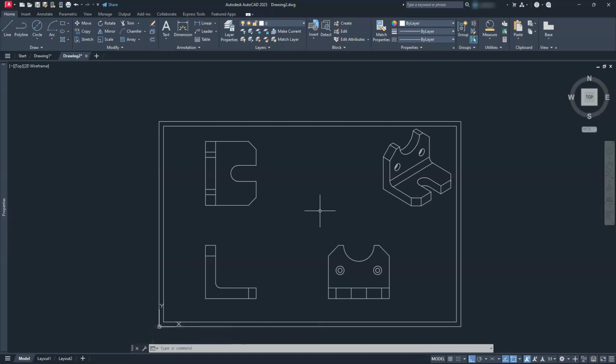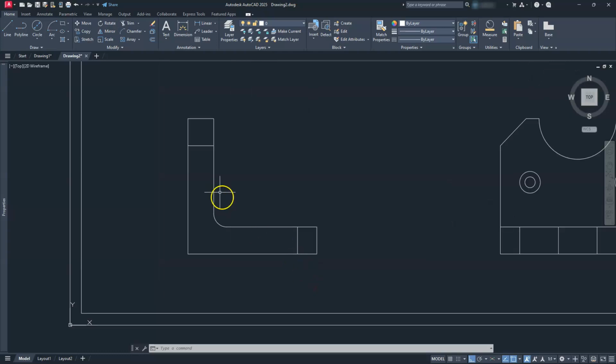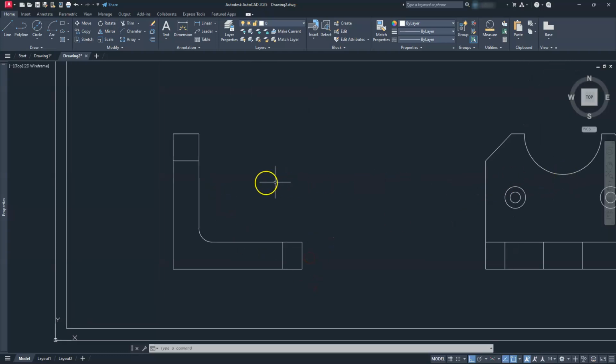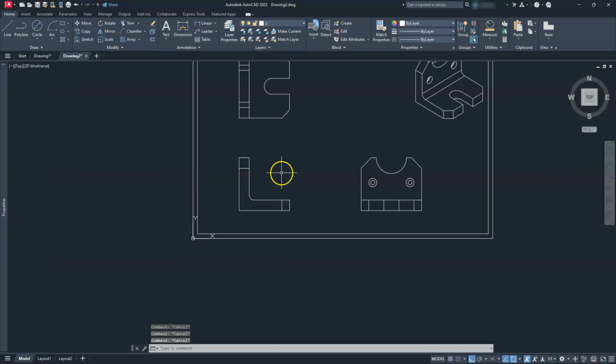But now before I do that, I want to decide, am I going to put these hidden features on here? And the answer to that question is going to be yes. So I'm going to go ahead and start doing that now on this one. When I look at this one, what I do know is that I have a hidden surface right below here, right? This distance going down from here is 30, or I can do a line. I can touch this midpoint, try not to touch anything else until I come here, select this intersection, and go right across to this one. Hit escape, and then this one will be a hidden line, right? So I can select this surface here and say, hey, that's going to be a hidden surface here.